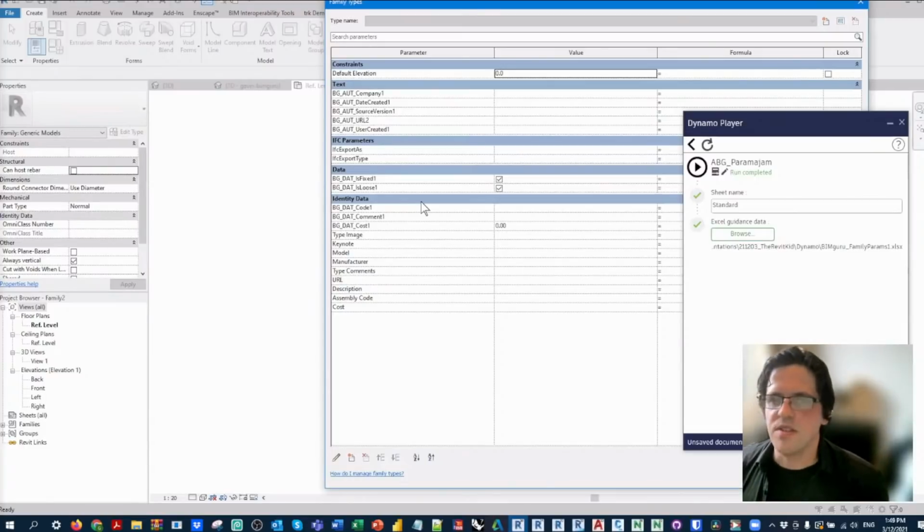And that saves me heaps of time. I also have a script I use that puts the dates and all these values in my authoring data. So that's my 1-2 combo, where I just go 1-2, and that's the family preset. You can also do things like detect the category of the family and make an IFC class table if you want to put IFC properties in there as well. With these, you can save so many clicks. I would have done this process so many times as a BIM manager when building a library. So this is one of the first things I wanted to solve in Dynamo.